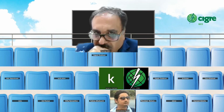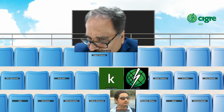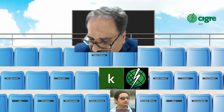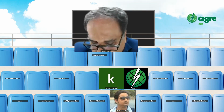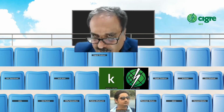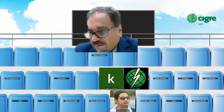Actually, regarding the question from Mr. Tariq about increasing gases, I believe you are having high ethane, methane, and ethylene. Is it correct? Yes, correct. Acetylene is not there sometimes. Yes, correct. So the overheating gases are available. Correct. So in thermal fault, basically you will not find acetylene, but mainly you will find methane, ethane, and some ethylene.